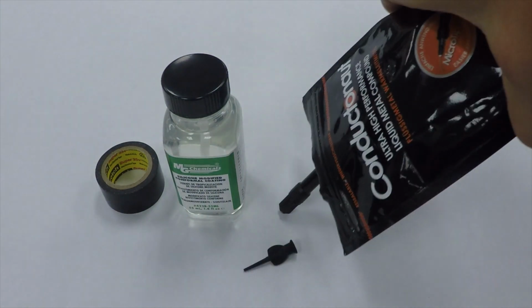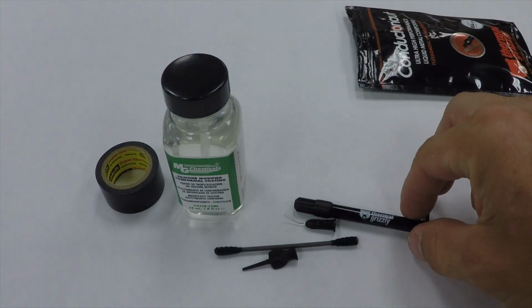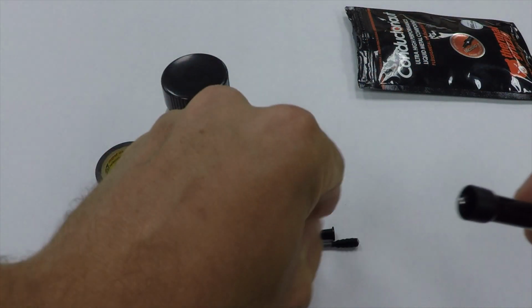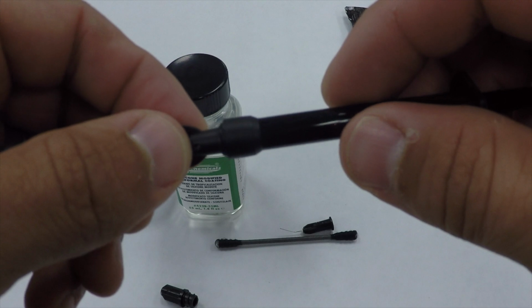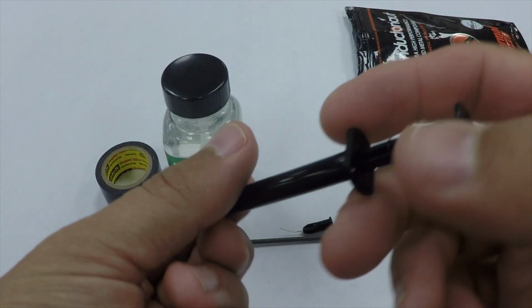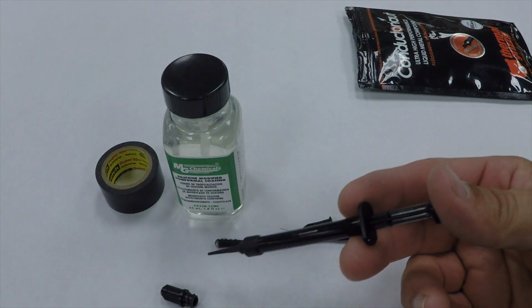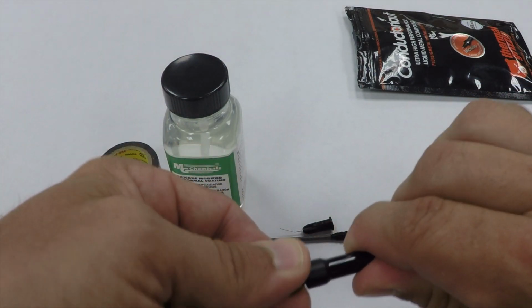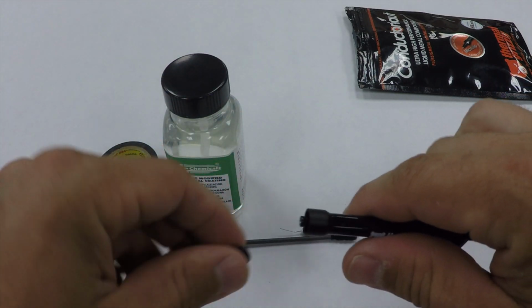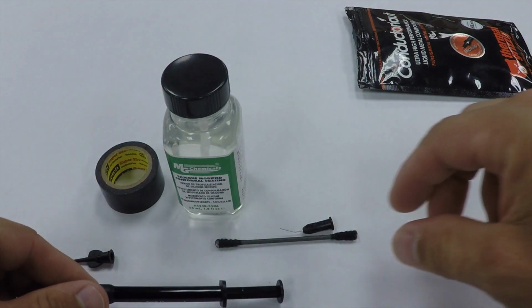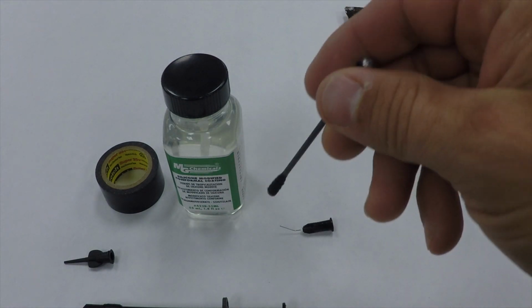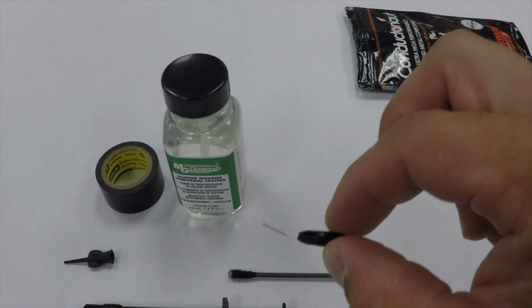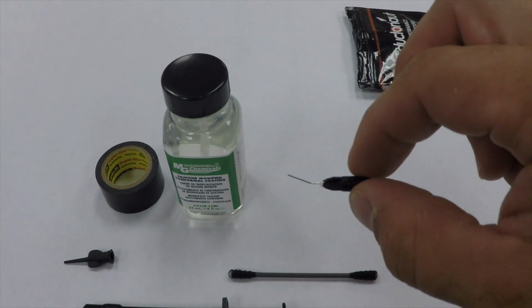Now when we open up the package and dump out the materials, you're going to see where the liquid metal is right here. And then you're going to unscrew the cap, and then you're going to apply this applicator tip, not the other one. And then it will squirt out, so you have to squirt out on another surface and then plunge it back in, and then you can take a very small amount and put that on top of the processor and GPU on your MacBook Pro. The Q-tips are great for moving around the liquid metal. You want to get a nice coating that's very thin. You don't want it to be watery. Do not use this tip.